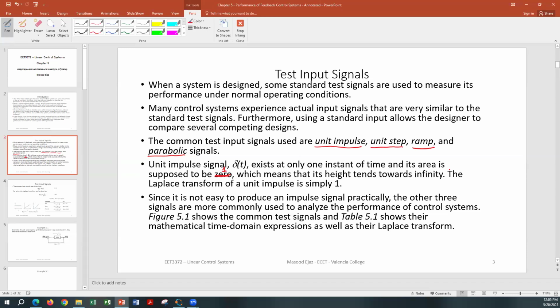Impulse signal is a mathematical signal. It does not exist because, again, a magnitude of a signal that is infinite does not exist in the real world. But approximations to the impulse signal are generally when lightning strikes, where a large amount of current flows in a very short amount of time. That's closer to what an impulse is in reality: some large signal taking place in a very short amount of time.